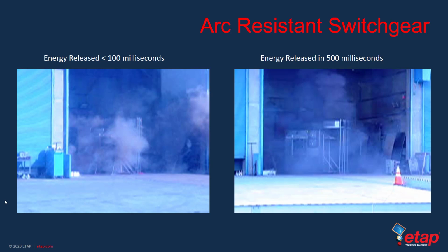As we can see in this video, both faults carry similar amounts of current, but their duration is significantly different. If the arc fault remains in the equipment for a long time under a current which is high enough, eventually the equipment could fail to vent or to even contain the arc plasma and molecular cloud away from the front of the equipment.